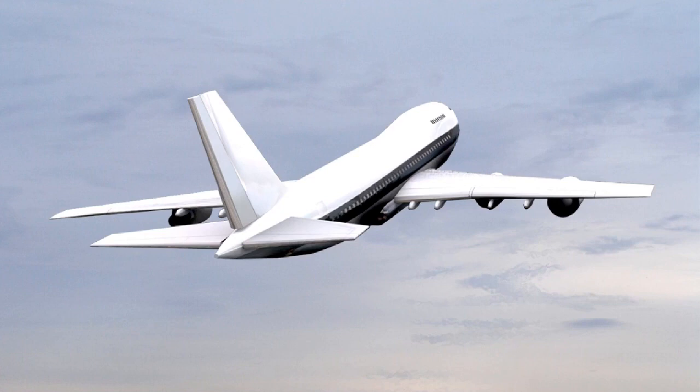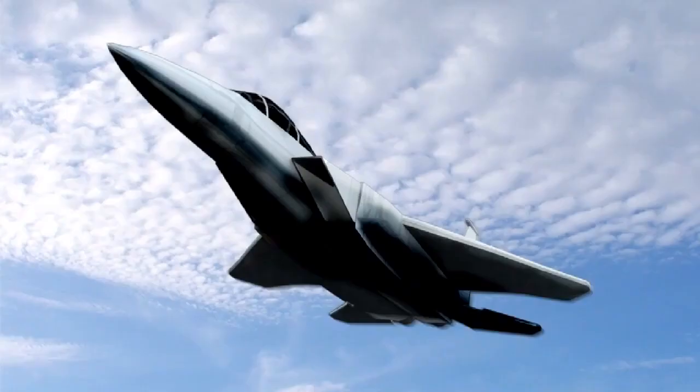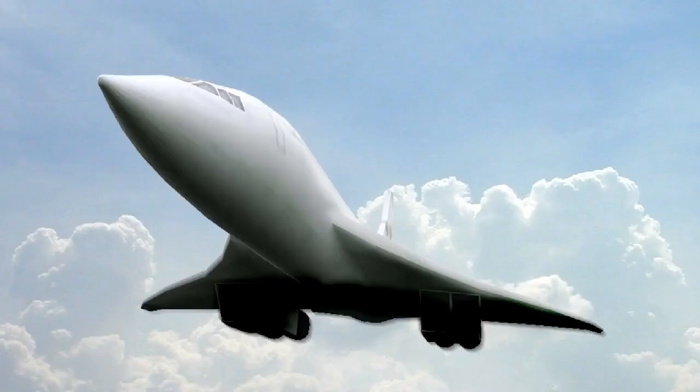Maximum continuous thrust. This power setting is the maximum level that can be used continuously. Maximum climb thrust. This power setting is equivalent to max continuous thrust, and is selected to give the best angle of climb speeds. Maximum cruise thrust. This is a power setting below the value of maximum continuous thrust. Maximum cruise thrust can be used, for instance, if the aircraft has to climb more quickly than normal because of a terrain clearance requirement, or in order to respond to a request from ATC for a higher rate of climb.